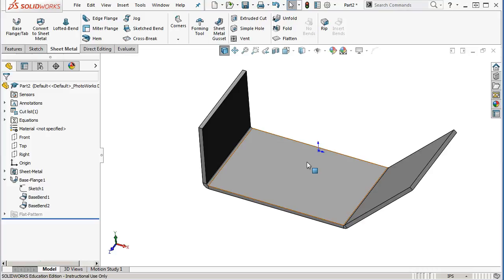I think the standard tolerance is plus or minus a 16th, kind of like woodworking is. You have plenty. We're going to let it shrink or grow an eighth of an inch overall in the worst case. So to say that it's for reference, no, I'm going to hold you to those tolerances. When we go out to, like I said, laser, water jet, plasma, whatever the process is, it's a reasonable tolerance. There may be some stack up, but it's within 15 or 20 thousandths coming off the machine.